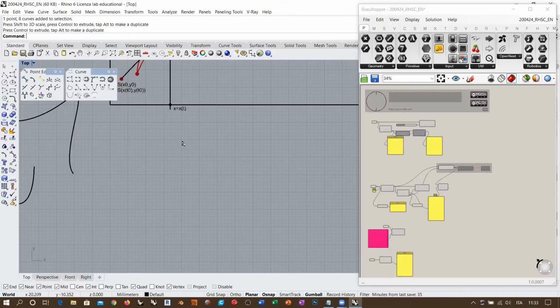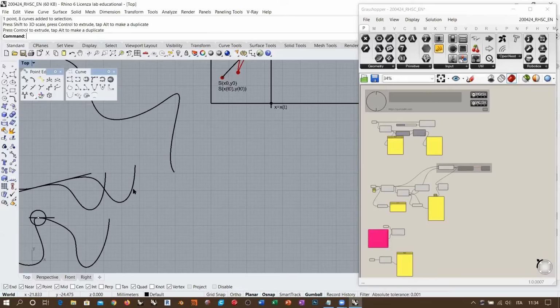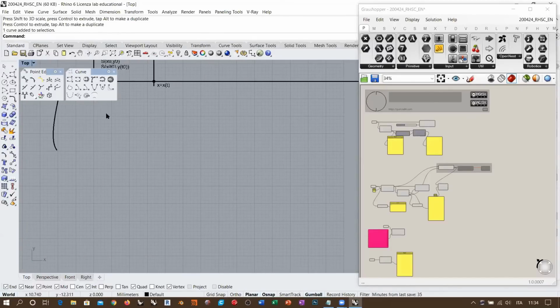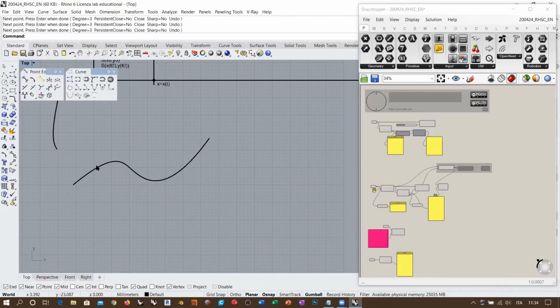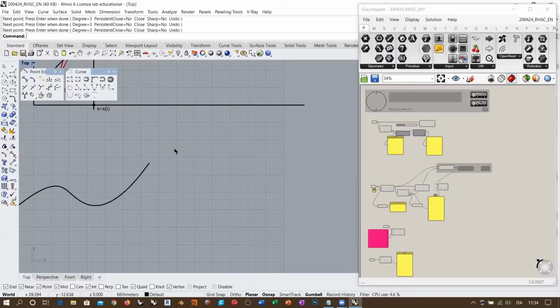Okay, so let's switch back to our NURBS curve. We saw that there is one particular rule, the first one, that allows us to define the tangency for a freeform NURBS curve with respect to another line. So let's say that we are working with a composite object. This is the first piece, and we want to create another piece of the same object, starting from the same point, and initially we are going to create it like this. So it's evident that we have a discontinuity here.